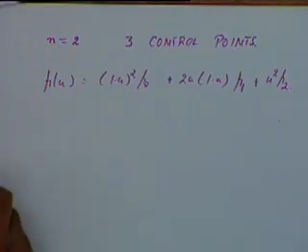Any questions up to this point? Why do we use Bezier curves? The first reason is to get higher degree curves, because in PC curves you are getting only curves up to third degree. If you specify more points, you will have to take a higher degree curve in that case. It won't be a cubic curve.